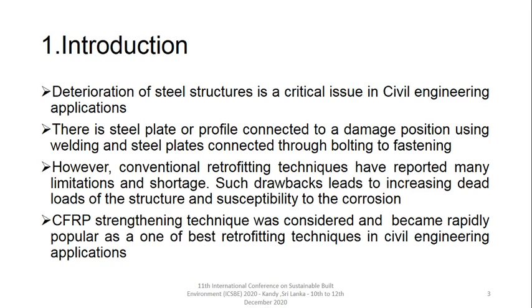Introduction. Deterioration of steel structures is a critical issue in civil engineering applications. There is steel plate or profile connected to a damaged position using welding, or steel plate connected through bolting or fastening. However, conventional retrofitting techniques have reported many limitations and shortcomings. Such drawbacks lead to increase in dead weight of the structure and susceptibility to corrosion.